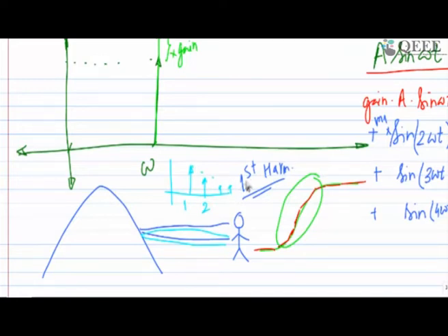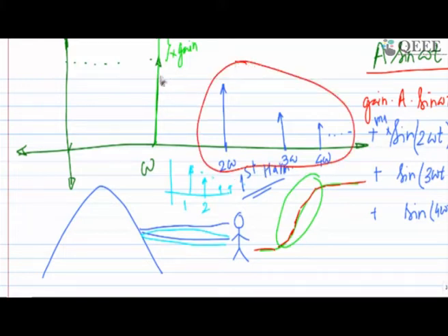So the same thing will happen in our circuit. You are not going to see only omega, you are going to see something at 2 omega, something at 3 omega, something at 4 omega, and so on. And these are the things which we don't like. Look, I want to see only a clean signal, this one, nothing else. These are the harmonics. These harmonics are known as noise, and this one is known as signal. So I want to keep my signal to noise ratio as high as possible.